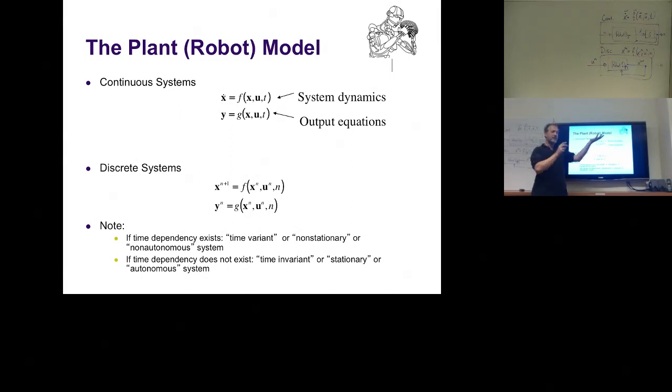Like, for instance, in a robot system which has position encoders in every degree of freedom, you can only measure positions. You cannot measure velocities directly. So your y would just be a vector of positions, but not velocities. And there are many other examples where you cannot measure many of the states of a robot. You will see later that we will need these equations to estimate all the states which we need for control. What we observe is often not enough for control. For instance, in many controllers we need velocities, so we have to get some kind of estimation going to obtain velocities.